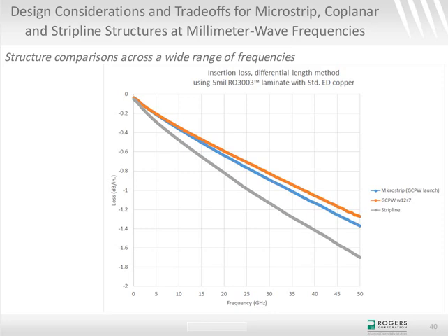And what they found was there are diffusion formulas you can use that predict, over time and depending on the temperature it's operating at, how long you have before the copper oxides migrate through the gold and make the gold really ugly and bad. So if you have a service time of like a year for your circuit, you could plate enough gold over the copper that in that time frame the gold's going to stay good. But it's just a matter of time before the gold goes bad with the copper oxides migrating through it. So it becomes a reliability issue.